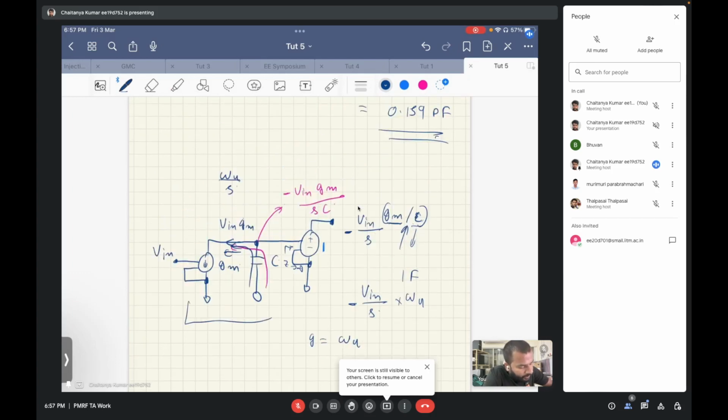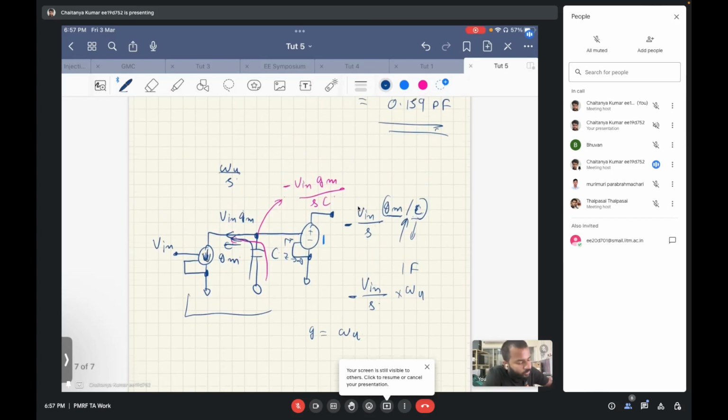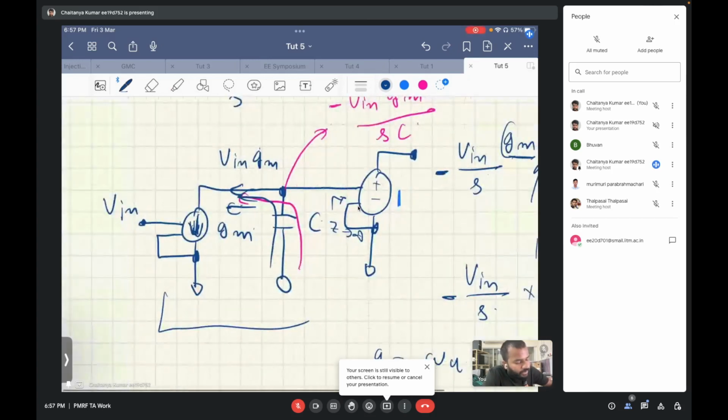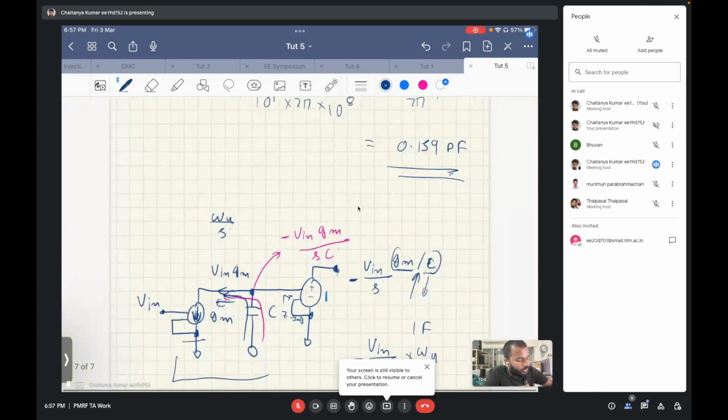So mind it, I am showing this with the direction of the voltage controlled current source that is pulling out the current. So this you should keep in mind. With this, you will get the inversion also, and you can now use it directly as the op amp, because since you have the inversion, you already have the negative feedback.